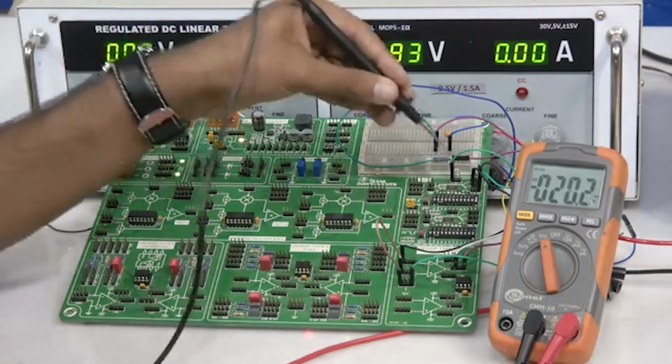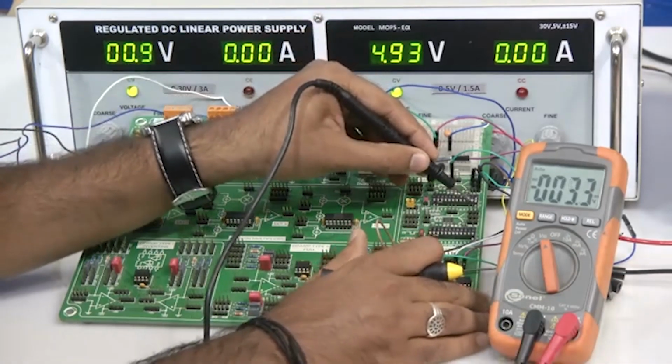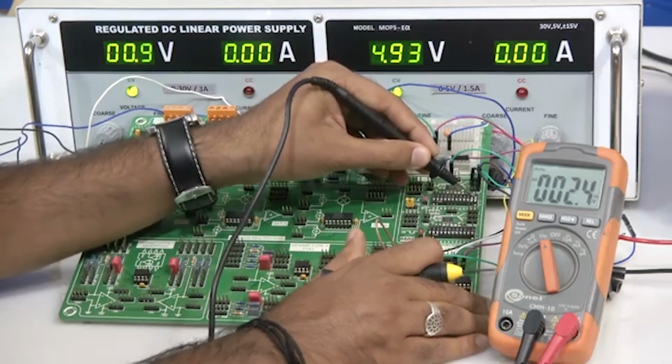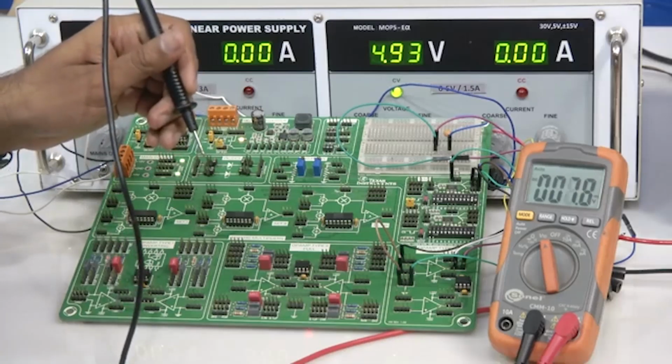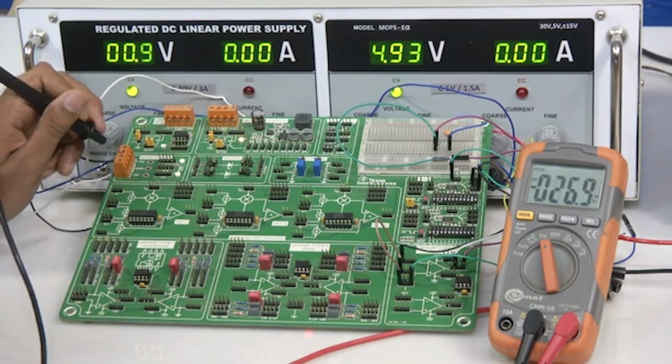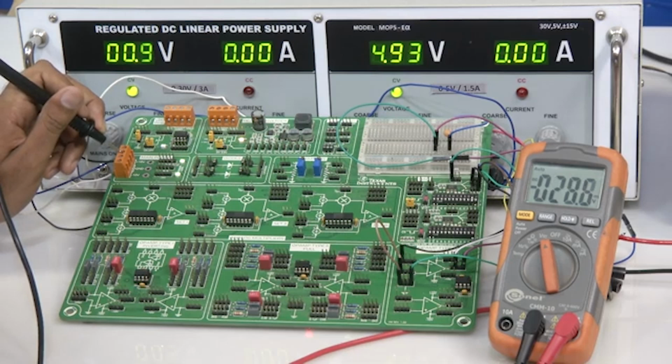Let us see what we are getting now. We will make the second bit 1 and make the first bit 0, so that we are doing only 1 bit change. Now we are probing it again. It was 26.4 before, now we are getting 28.8. So, it is around 2.4 millivolt change, roughly we expected around 1.5. So, we are getting in that range the voltage change. Remember that this is in millivolt range, so noise components also will be there, but we are seeing a change.